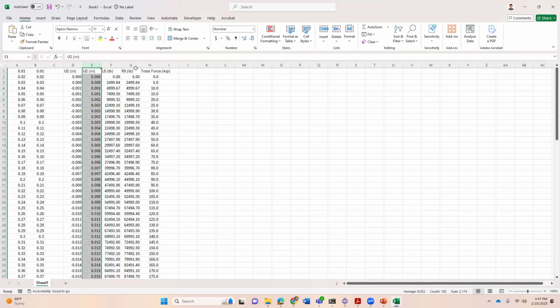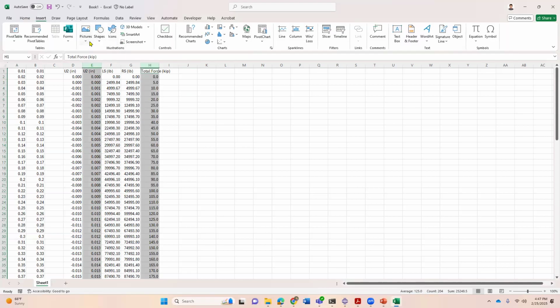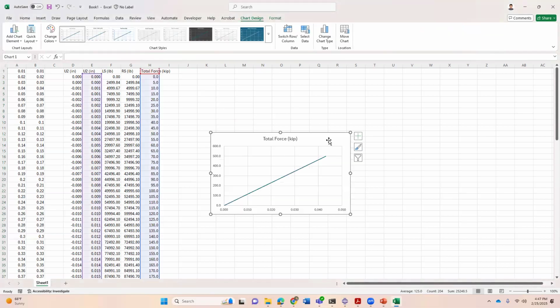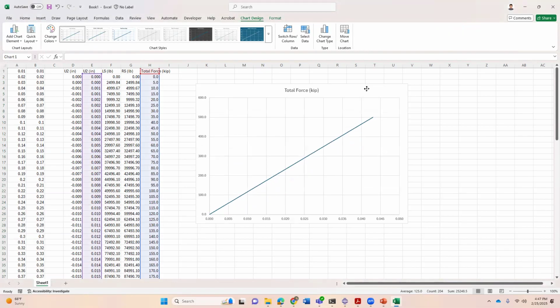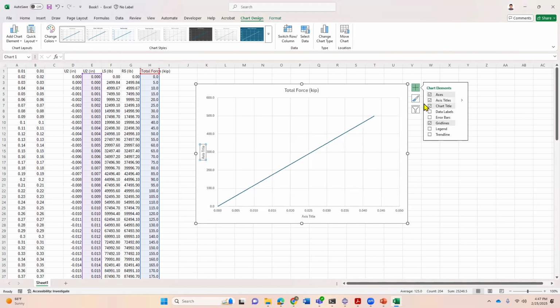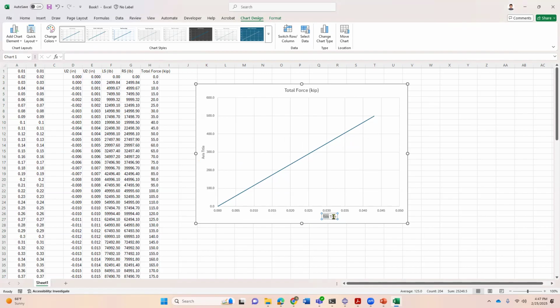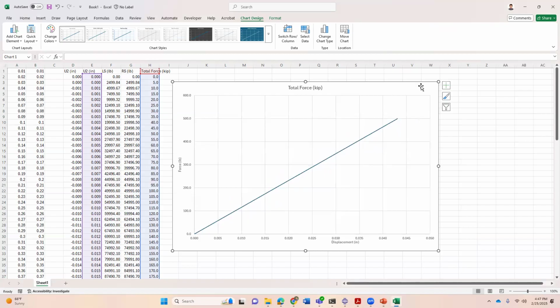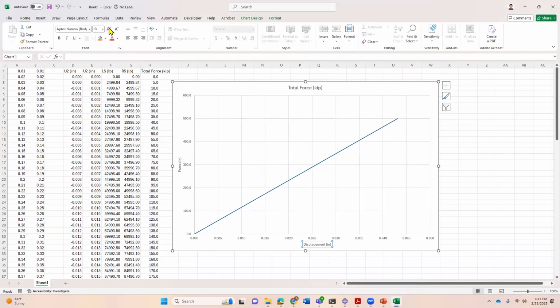Anyway, let's plot the force versus displacement response, although this is not very significant for this beam. But what I want to show here is the vertical axis is load and horizontal axis is, sorry, that's displacement in inch, right? As it's a linear beam, you can see the force increased linearly with displacement, and it should be. So for a linear beam, because we have linear material properties, the force displacement response is linearly elastic.